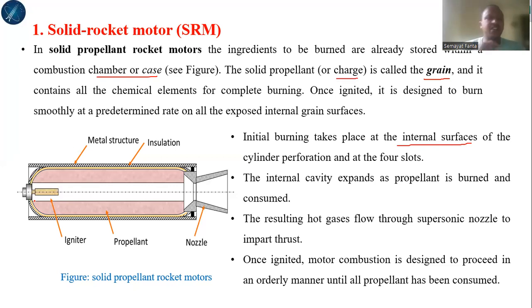I forgot the technical word. So it is opposite to that. But most of the time, the progressive burning is expected. Why? Because we need to accelerate our vehicle more and more. So there are different shapes of propellants that give different types of burning rate. So burning rate is also one of the criteria that we can calculate.